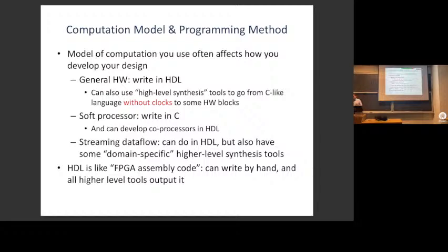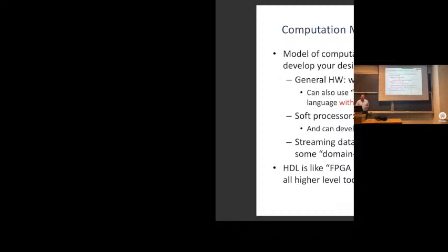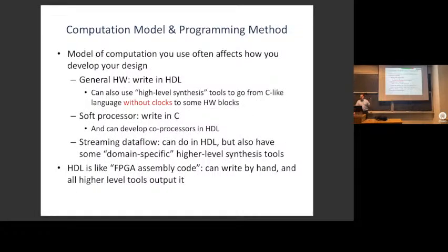The definition that I use is it's without clocks, okay? So in hardware description languages, you are saying, here are my registers. There are clocks. So you're deciding what goes in a clock period. In a high-level synthesis tool, you will not see a clock. You will see for loops. You will see computations. You will see pragmas that say things like, do this in parallel or pipeline this loop. So you'll see things like pragma pipeline, pragma parallel. But you will not see clocks. So the tool decides where am I going to put the registers, which defines where are my clocks.